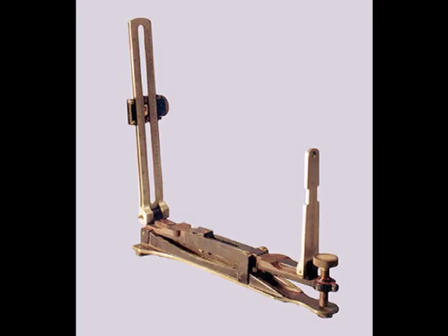One of the 2 upright flaps has a sighting hole where the observer places his eye when sighting the object. The other flap has a long slit and is graduated along both edges. One edge bears the trigonometric tangents and the other the degrees of slope, but at the middle there is a common 0, so that the 0 and the sighting hole are in the same horizontal alignment.